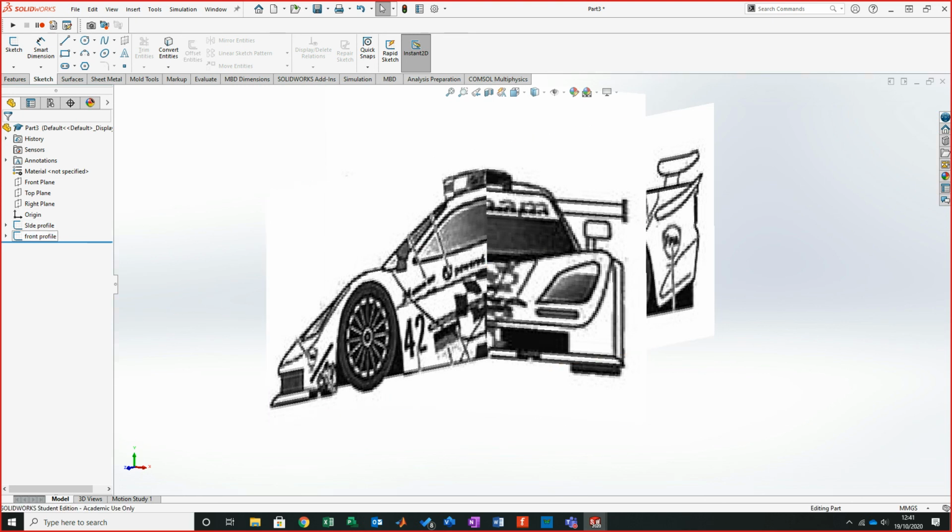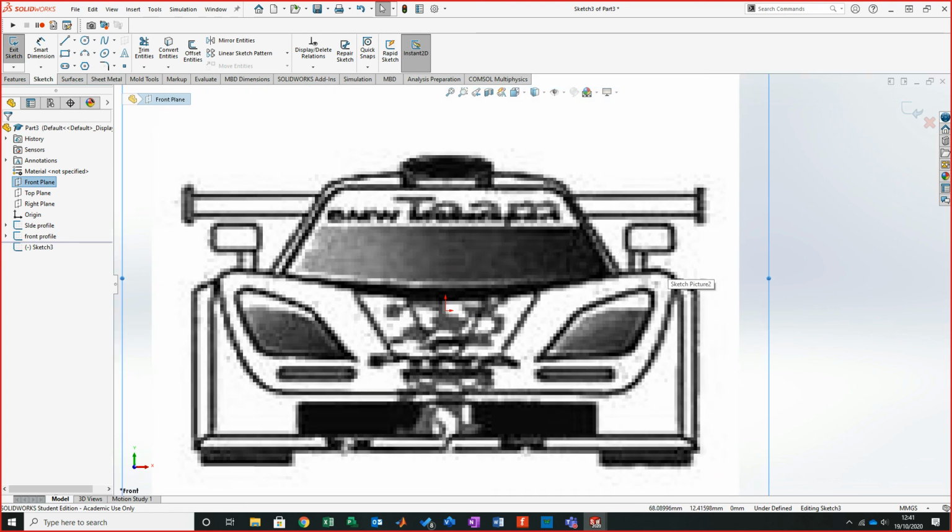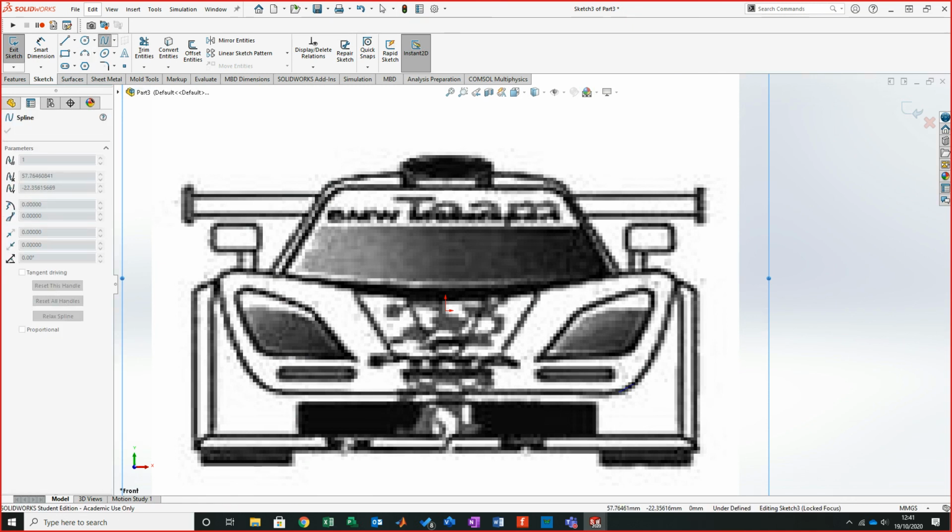now these are separate. If you do this at any time, do not draw straight onto them, ever, because this will connect the sketches as well and make your life difficult to interact with. So what I'll now do is sketch again above. Now what I'm attempting to do is get this edge, so if I click on sketch, Control A, I'm attempting to get this spline, if you will, that edge there. So I'm going to click there, there, and I'm literally just tracing up the edge.